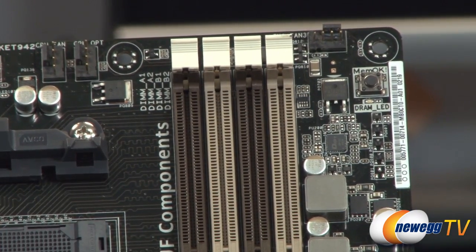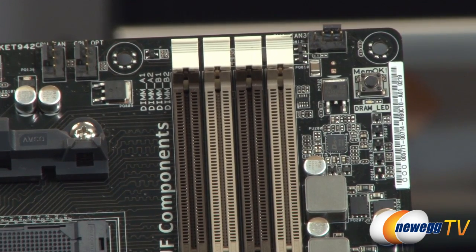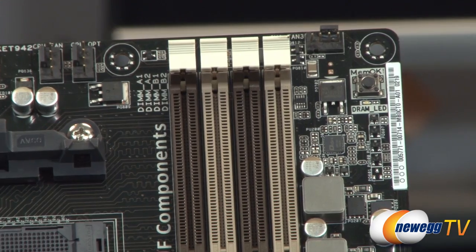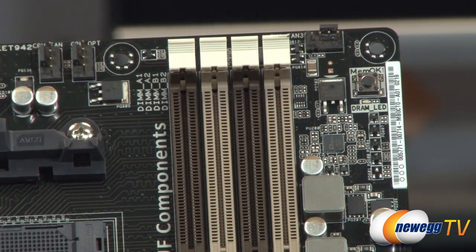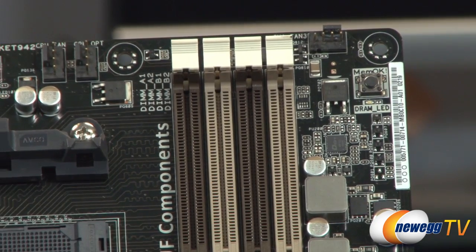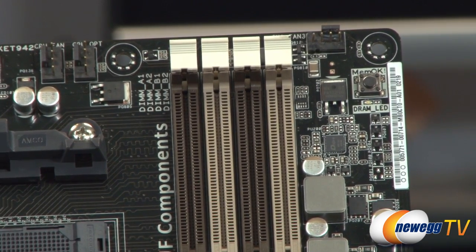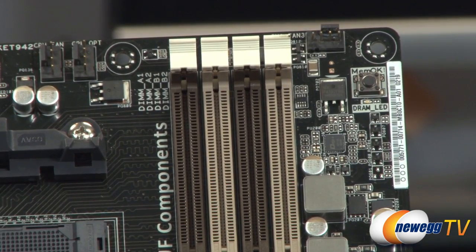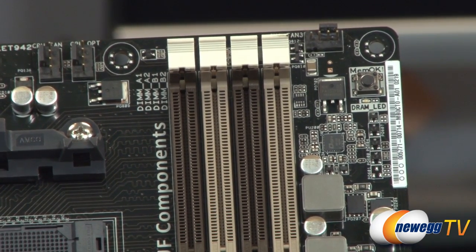So this is something we've seen from Asus as well as some other motherboard manufacturers. Kind of like that debug LED readout that I showed you, but these are specific to certain components on the board. So if you're trying to start up and it's freezing on the memory initialization, that DRAM LED will light up, and again, that's going to help you out with troubleshooting. So those are some examples of some stuff.